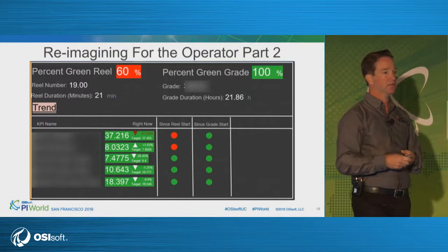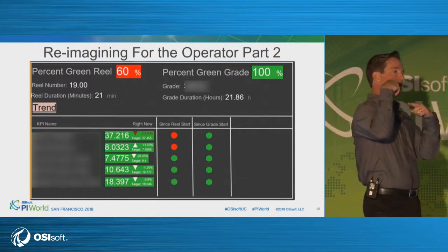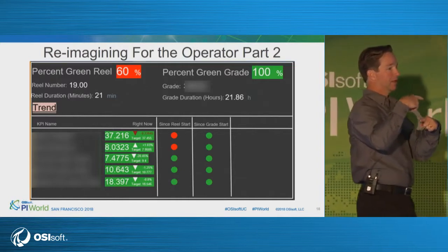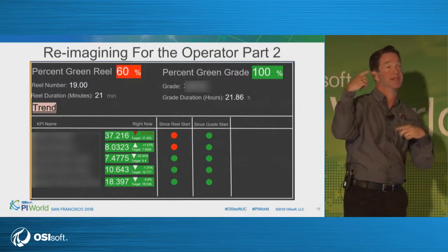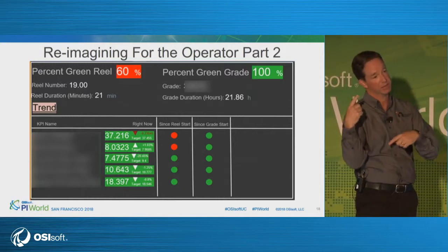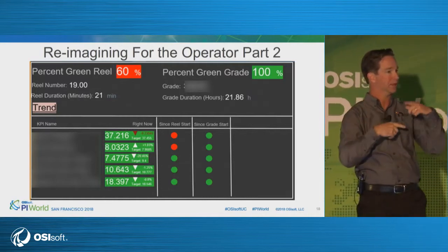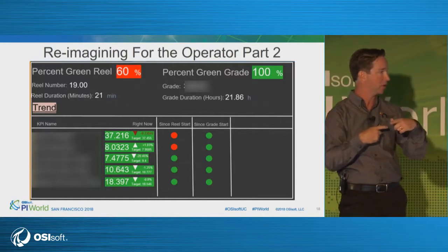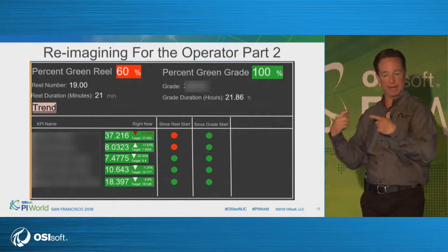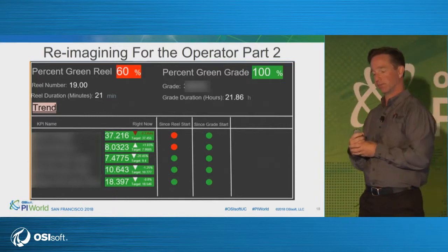And if it's green, you're within your specification limits. If it's red, you're outside of your specification limits. Actually, I'm sorry, I apologize. You're out of your control limits. We're not getting too sophisticated yet. Maybe between spec and control, we're probably going to turn that yellow. So it gives you like a warning indicator to say that you're out.